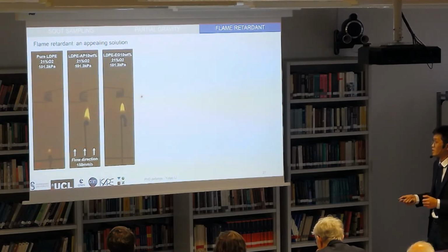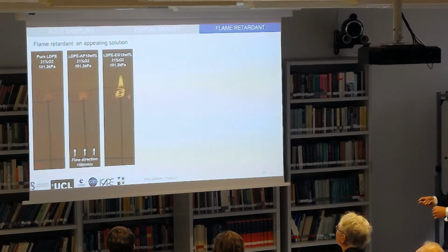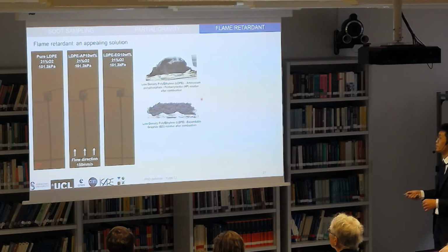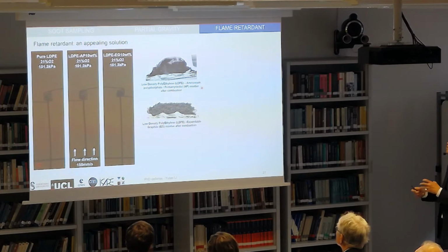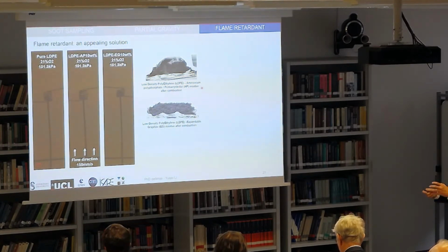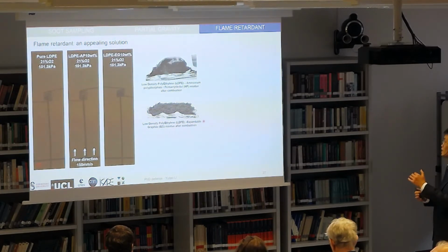The intumescent can be obtained by a series of chemical reactions, such as AP in the middle of the video, or using mechanical expansion, such as the EG on the right side of the video. Two figures here show the post-combustion residues of these two flame retardants. For the AP residues, an internal structure is forming with small and large voids, and the cohesion of the structure is relatively high. For the EG residues, the cohesion of the structure is high enough to provide thermal protection, but it is not as strong as the AP residues.